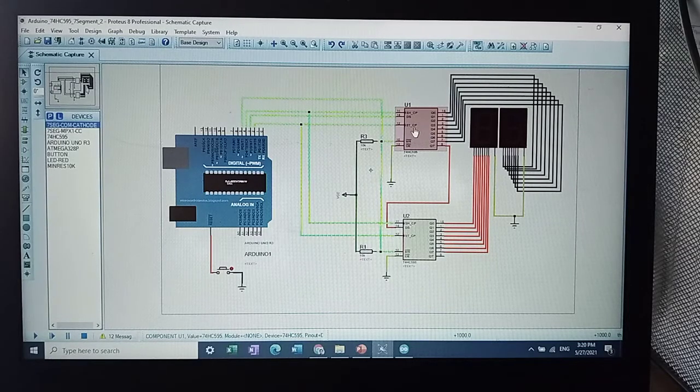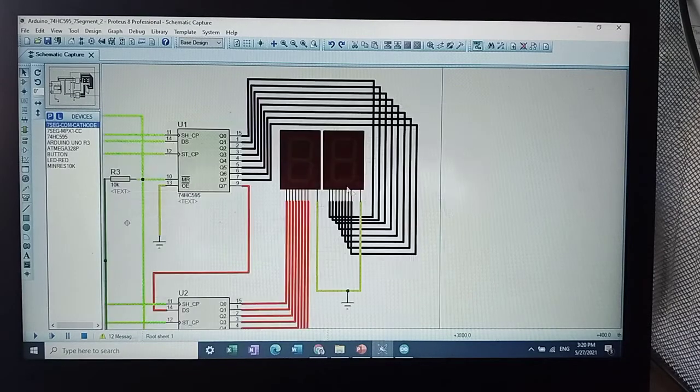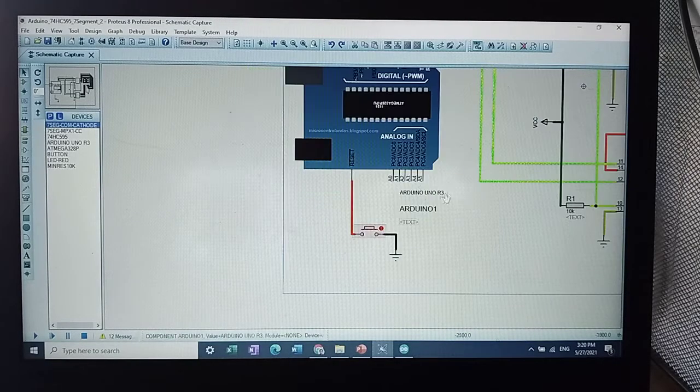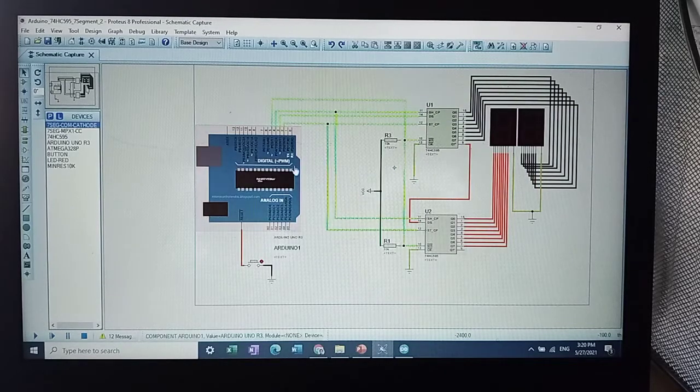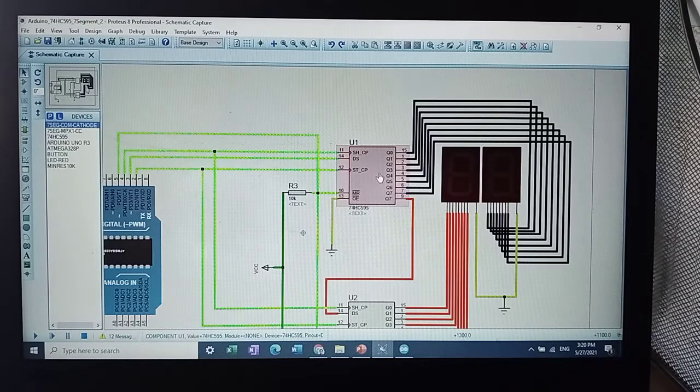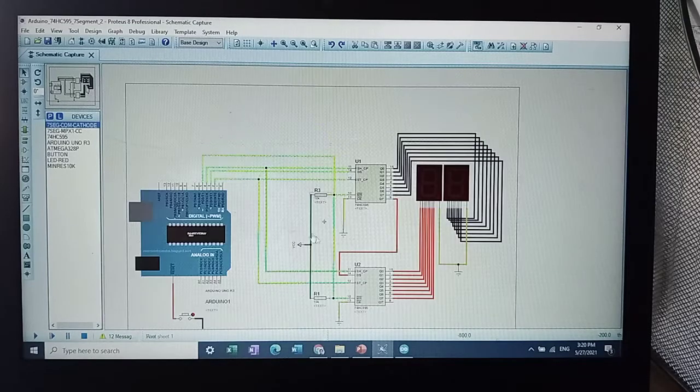It will fill the information capacity of the 74HC595. So again, because we are dealing with digital data, it needs to be able to present that BCD, the binary code, into a decimal output, which is from 0 to 99. So again, there's a reset button. We will use that later. I didn't use any analog pins. It's all digital pins. And the good thing about using the 74HC595 is that I'm only using 3, or we could say 4 pins in total.